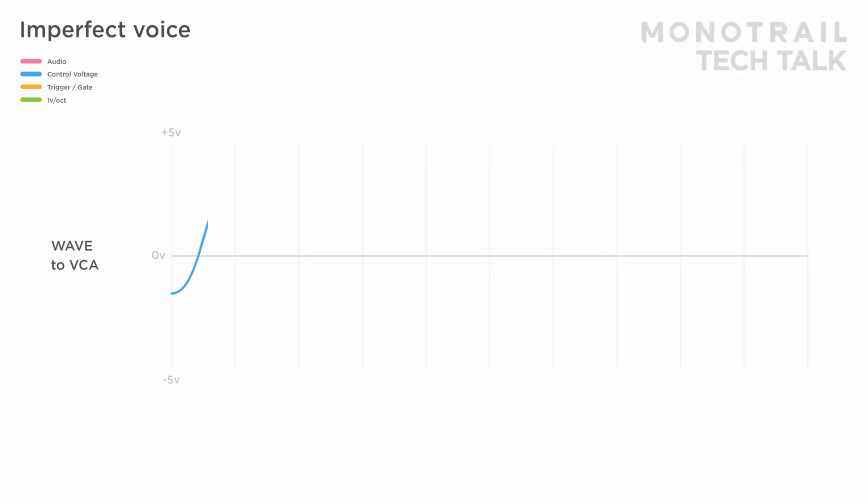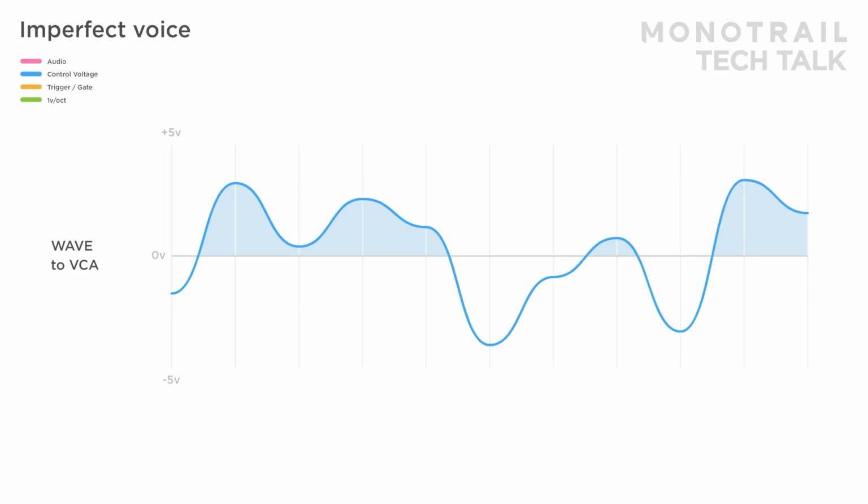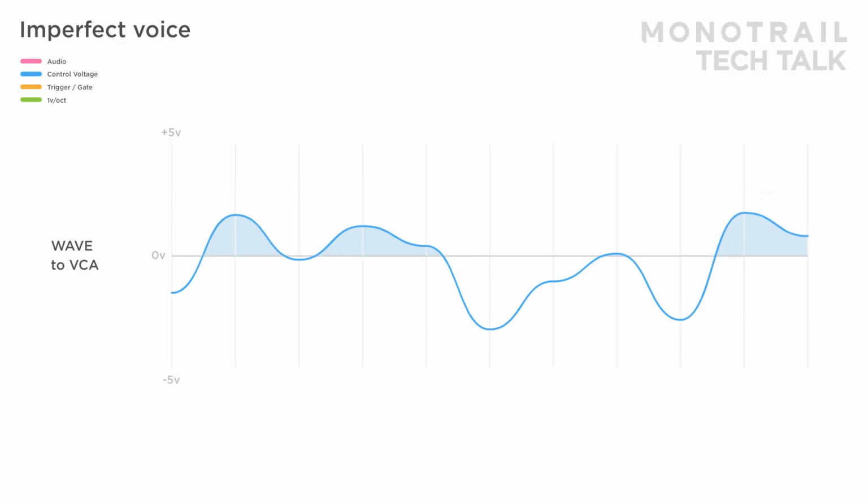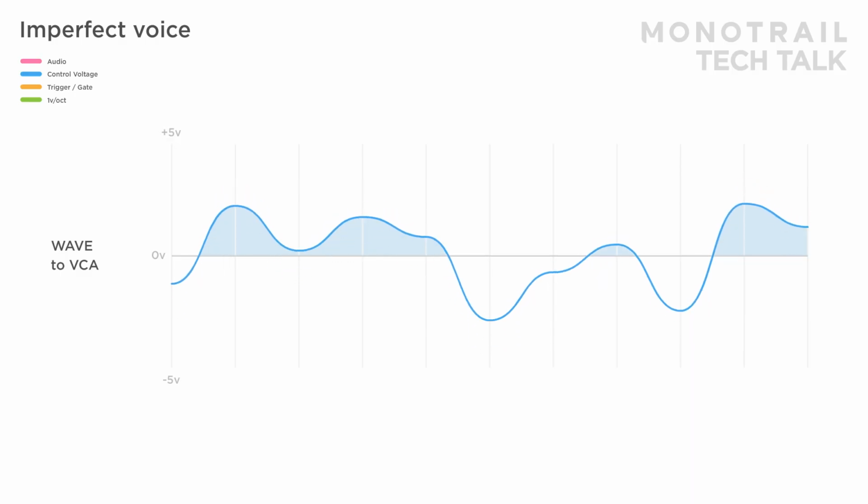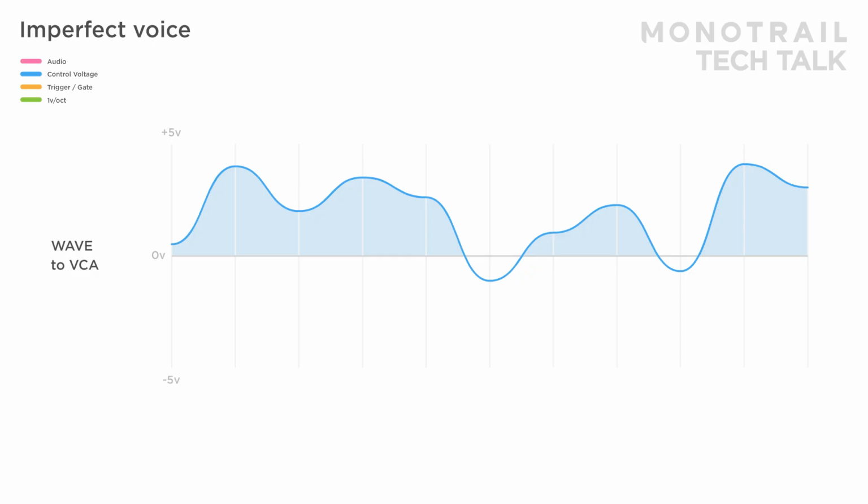Just a quick note, if you use a bipolar random voltage to open a VCA, only positive voltages will allow the input signal to pass through. In this FM patch, that means that when the random voltage is below 0 volts, the pitch is stable. This is good because that creates only occasional metallic drifts. By adjusting the level and offset of the voltage on the module, you can control the amount and depth of modulation very accurately.